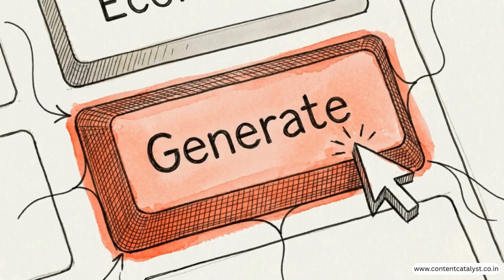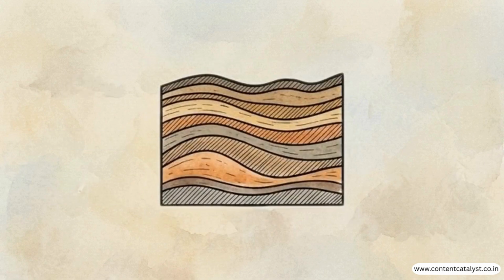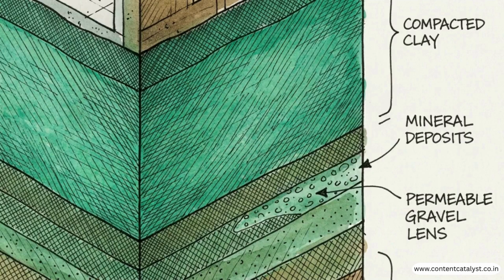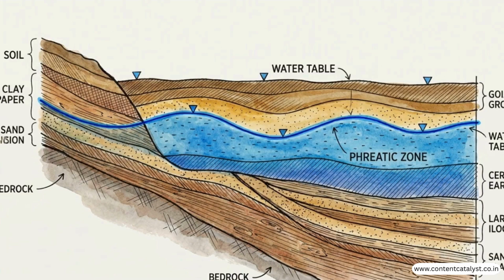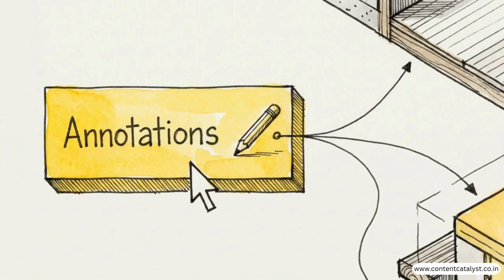Once zones are assigned, the critical next step is clicking the Generate button on the toolbar. The software instantly fills the empty geometrical spaces you outlined with industry-standard hatching patterns and colors based on your assigned GT parameters. Hitting the Generate button confirms your raw geometry is successfully married to your material data, producing a true geotechnical model. With the soil defined, use the exact same line drawing method to map out the exact groundwater levels across the site. To detail your schematic, navigate to the left toolbar and click the Annotations button.